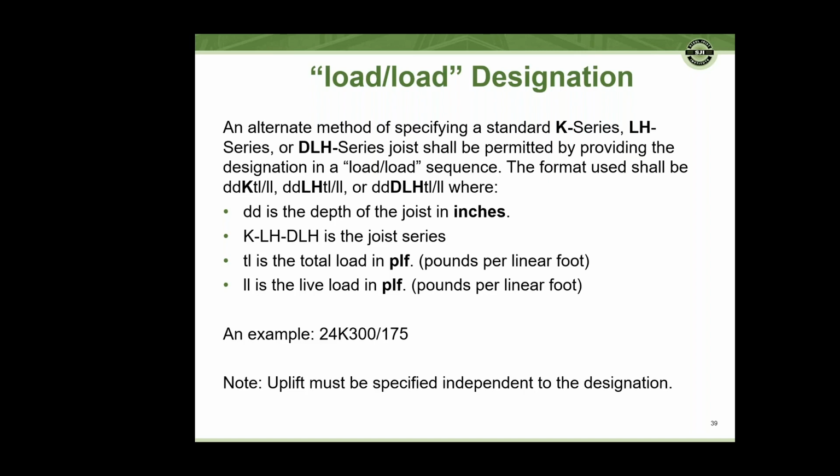So an example is 24K300/175, where it's 24 inches deep. It follows the K-Series rules, but it needs to support a total load of 300 PLF and a live load of 175 PLF.